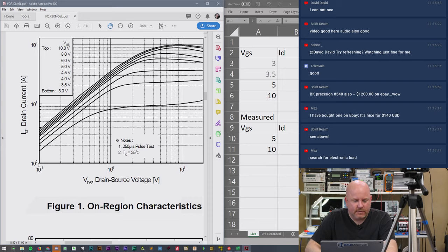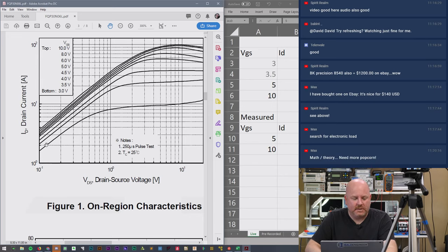So this is 1 volt down here, and then 5 amps through the drain. So this is 1 amp down here, so that's 2, 3, 4, 5. So this line is going to be the 5 amp line. And this curve is the VGS when it's 3 volts. So what this is basically telling us, if we just make it easy, I'm going to say it's this line.